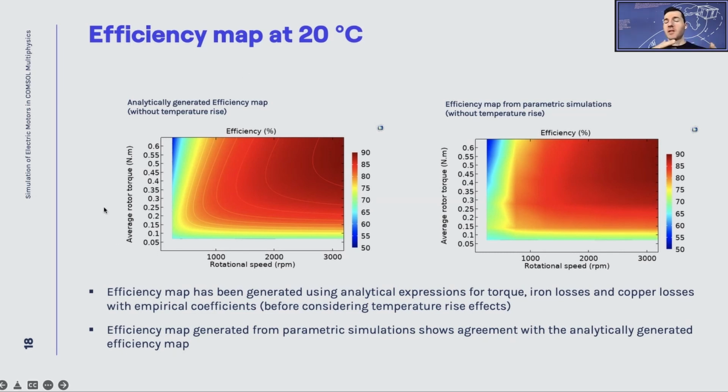So you can put this equation into COMSOL and you can generate this figure that you can see here on the left-hand side. And here on the right-hand side, you can see the numerical solution that we mapped from the COMSOL solution. So here you can see the same efficiency map, and it matches quite well what we can describe with an analytical approach. So we can create the same efficiency map in COMSOL Multiphysics. That's what you could do with an analytical approach here.